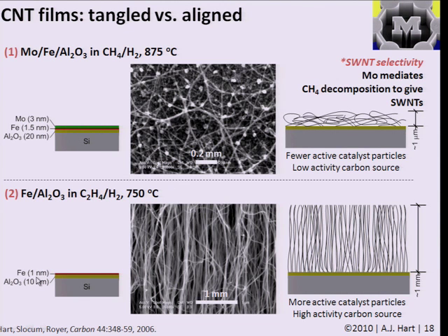You could imagine that the density of the catalyst and the growth time would affect the topology of this network and its final electrical properties. Also, the purity of the atmosphere or the amount of amorphous carbon on the surface of the nanotubes might also affect the final transport. It might determine the contact resistance between one nanotube and another nanotube in this film.